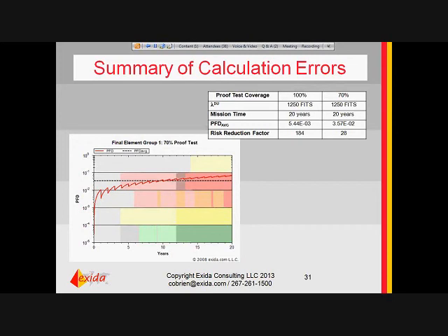If your proof test includes a leak test across the valve and a timed closure, then you're going to be achieving 98-99% proof test coverage. If your proof test includes a partial valve stroke or a full valve stroke of the valve, you're going to be more in the 70-80% coverage range. So the design of those tests is very important to the overall achieved safety of the system.